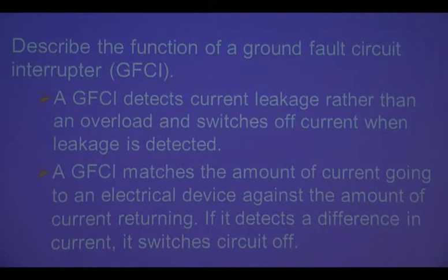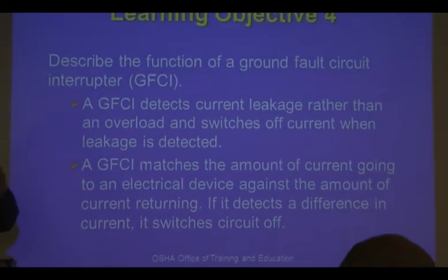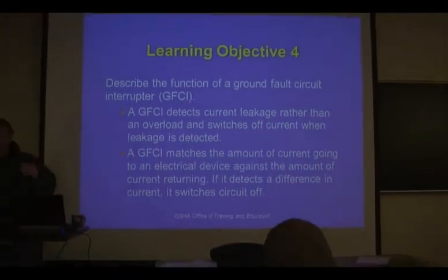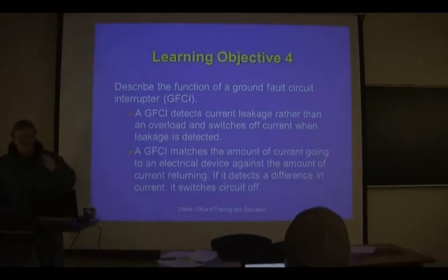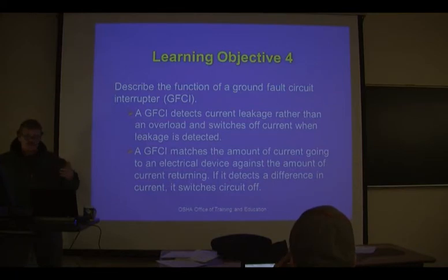It depends on what kind you have. That current is called leakage current. It's not the same as a short circuit. A short circuit is huge amounts of current, right? GFCI protects against leakage current. That's a small amount that's leaking through some low resistance connection somewhere, okay?